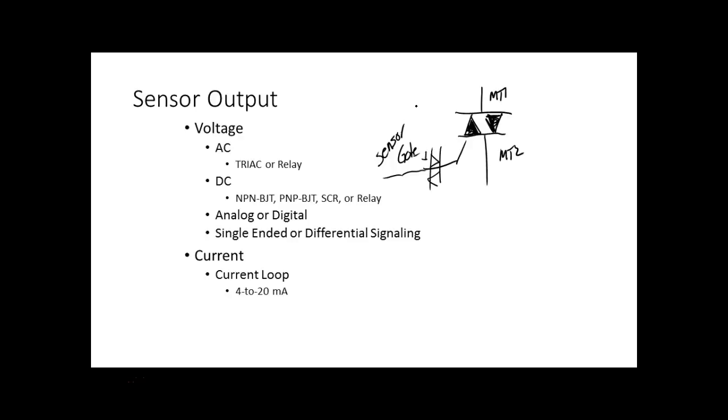The triac has what we call a breakover voltage. When you turn these things off, there is a path that you can get through. And if you exceed the breakover voltage on a triac, it will break over and it will be bad. That's not good. So relay outputs have the advantage of what? Yeah, they're usually not dedicated to a voltage. I mean, we can put DC on, we can put AC on. We've got some solid state limit switches that don't care if it's AC or DC because they use what? They use relay output.